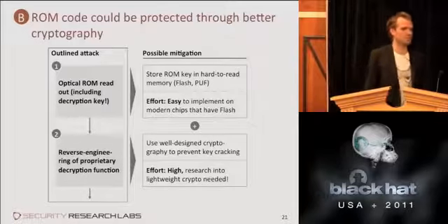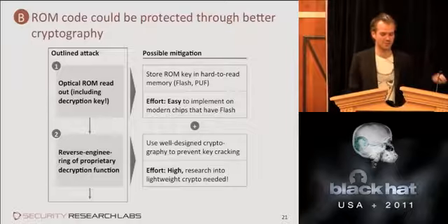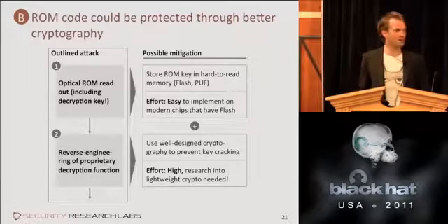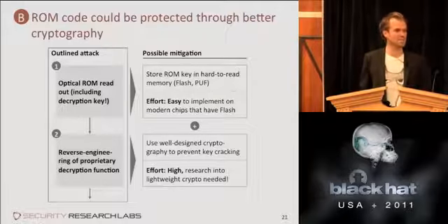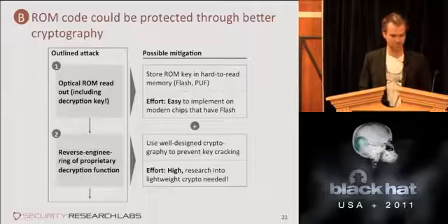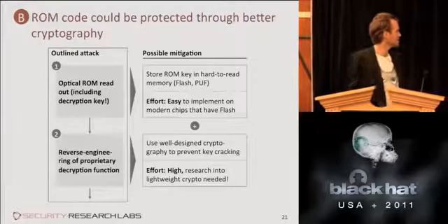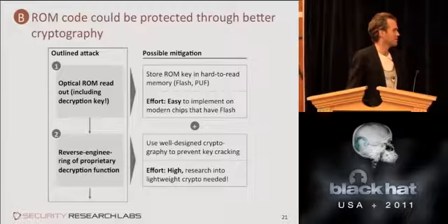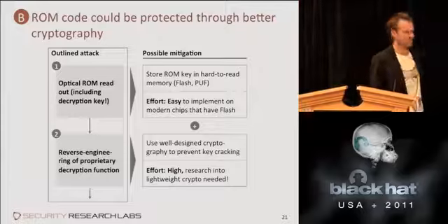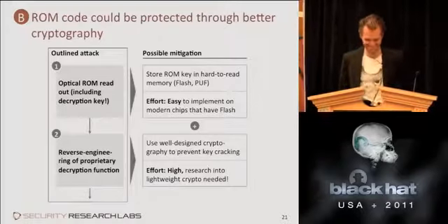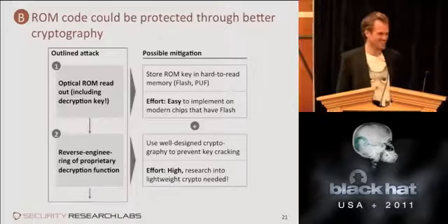And this being a 64-bit key or a little bigger if you want to be future-proof, let's say you spend 128 bits of flash on storing the ROM key. There's already many dozen kilobytes of flash, so it certainly wouldn't hurt cost-wise. There's already 64 bits at least of trace data from the factory that could be half the key anyway, and then have another 64 bits of space. True. Yeah, that's a good idea. Yeah, of course. Write a patent on that.